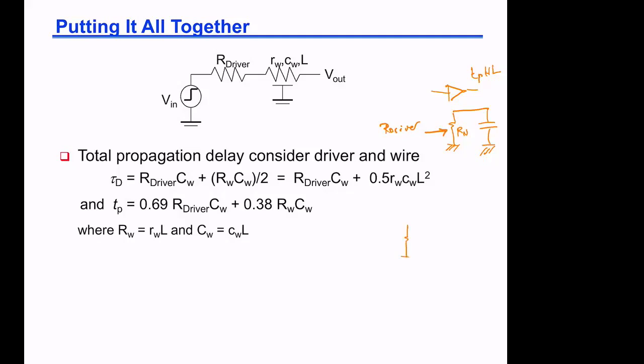I have a resistor that is connected to ground, and then the switch will close and it will start to discharge the capacitor. Here, instead of saying the switch will close, for example, here they're taking the case where the output will go from low to high, and they decided to apply a step input going up. Of course, our input doesn't change gradually; it connects to either VDD or ground, but the switch is turning on or off, and I have the R driver and then the wire, and they're asking me to find what is the propagation delay for my circuit.